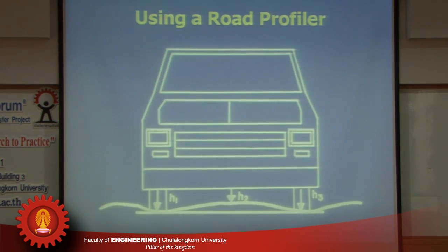Well, this could be done quickly using this high-speed profiler. Basically, the laser sensor needs to be placed at a distance where it corresponds to the wheel path.